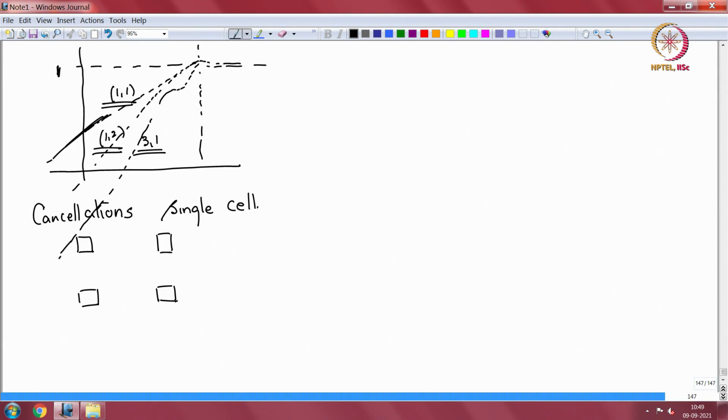Okay. And this non-dimensional frequency is given the term gamma, and it is the acoustic wave number divided by the square root of (p pi by a) whole squared plus (q pi by b) whole squared, which is the modal wave number.